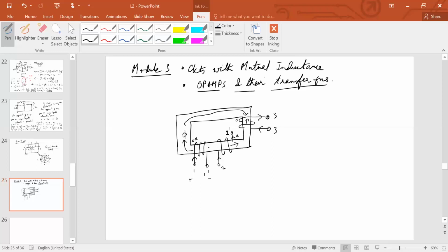what should be the direction of the current flow? So you can check that even then the current must leave through this end. But if the current leaves through this end, this being now the source of the EMF, this becomes a positive terminal. So once again, these circular dots check out. The triangles are representing the polarities of the mutual inductance between 1 and 2. The circular dots are representing the mutual inductance between 1 and 3.